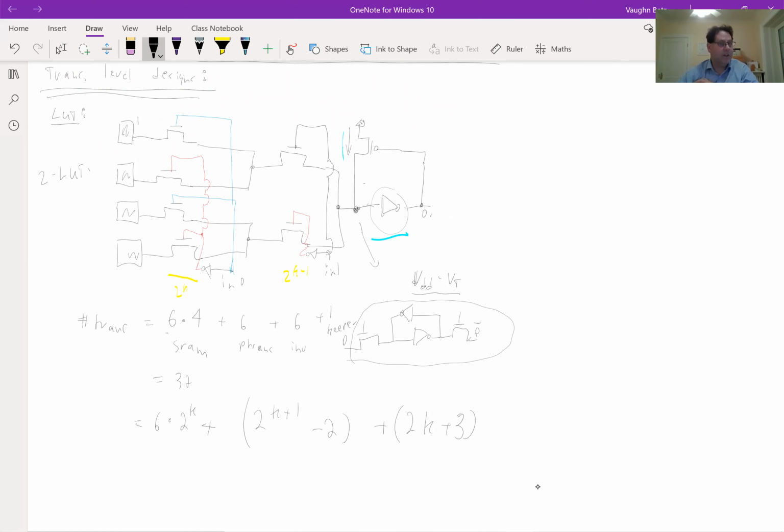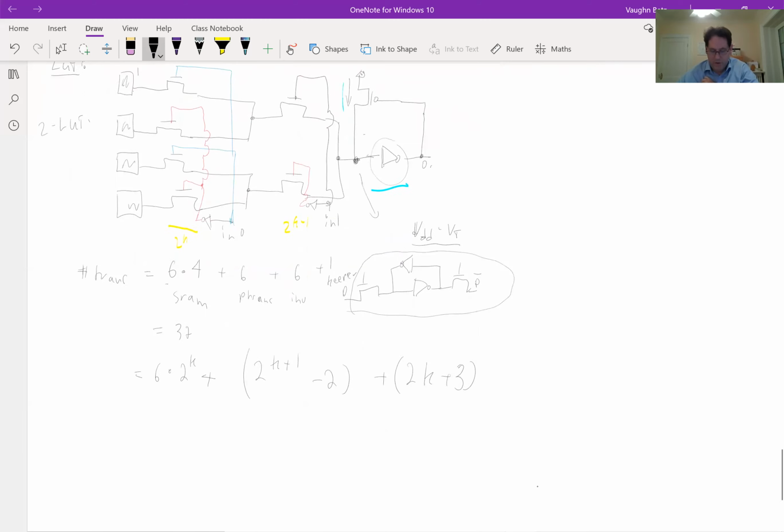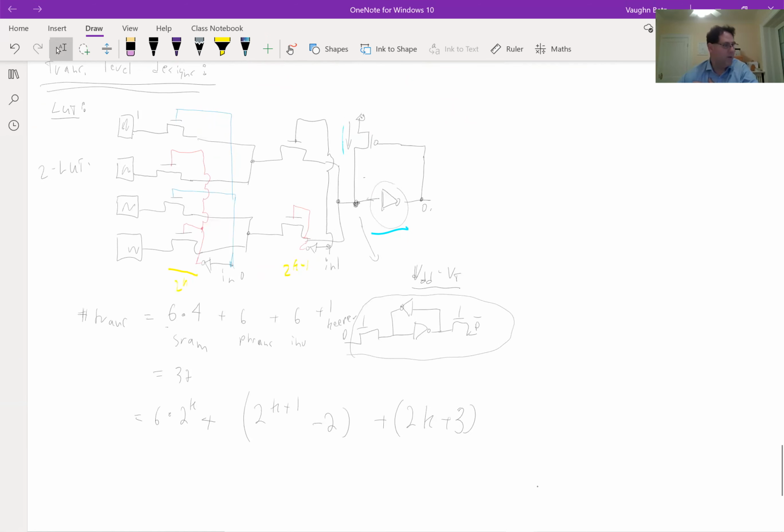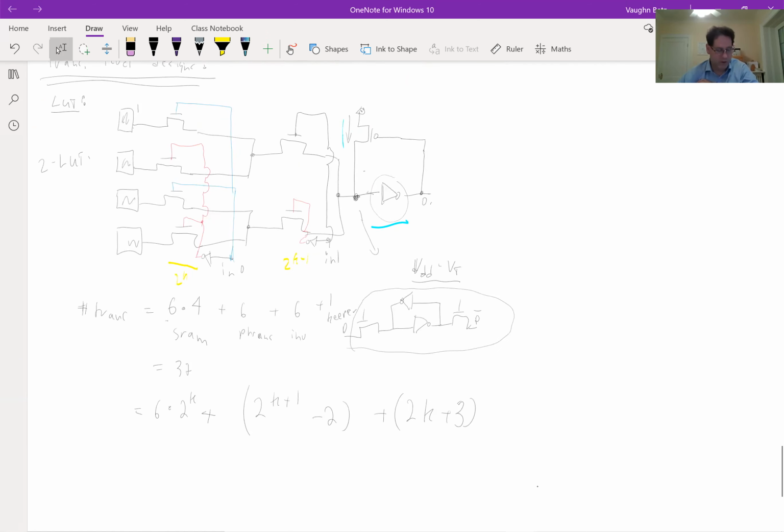And the layout of a SRAM is really optimized because you repeat it so many times. This is one where commonly companies will basically violate design rules and check that it's okay to get a more dense layout. So for the SRAM, we can assume they're all minimum size transistors, so six area units. Even if some of them aren't quite minimum, the layout is so dense we can assume 6.